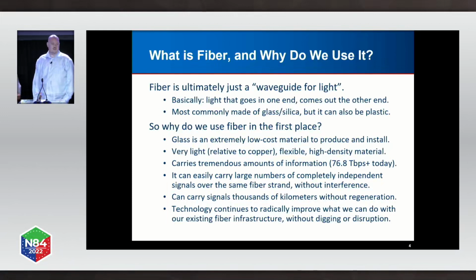The big reasons to use fiber: it's very low cost. You can make very cheap, very long, very high count cable, thousands and thousands of strands of fiber in a very small cable. It's very light, especially compared to copper, so that matters for shipping, logistics, putting it on a boat, deploying it in the field. It's very easy to work with. And you can carry a tremendous amount of information.